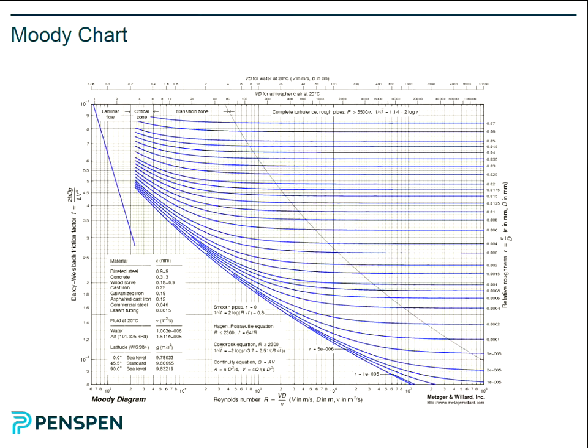So I think the lesson from that would be that when you start off, you might have 0.05 millimeters. But the trouble is, when it becomes corroded, it might end up being 1, or might even end up being 5. So the danger is, you need to really consider the corroded condition when you're considering the hydraulics of your pipeline, particularly if it's very sensitive to roughness. To consider clean steel is fair enough, but it's not going to stay clean steel for very long.